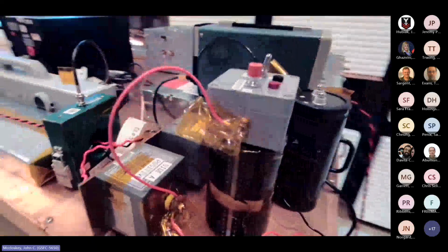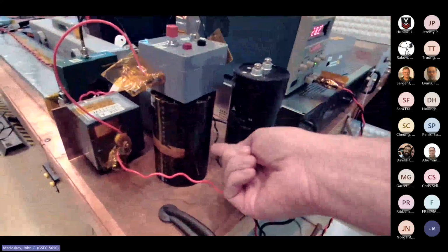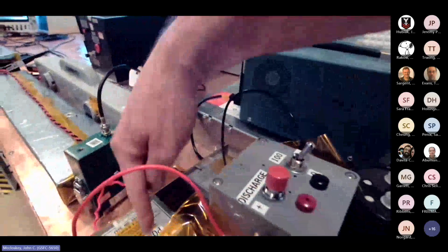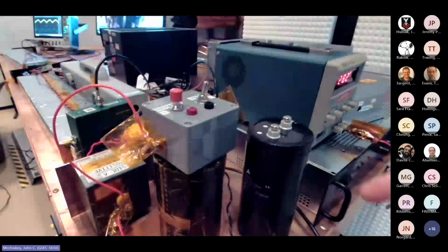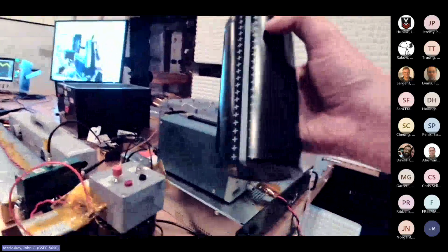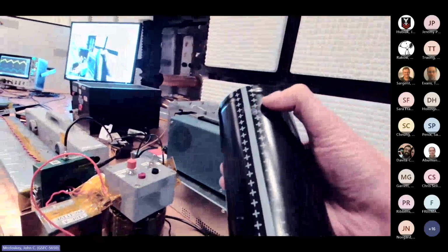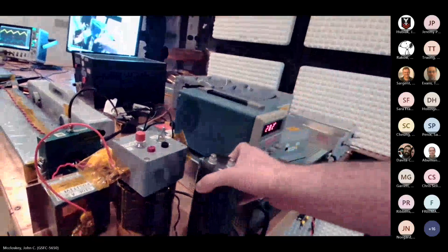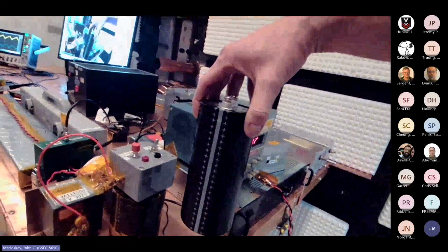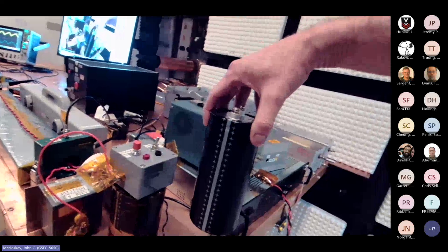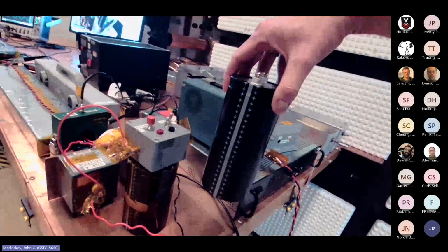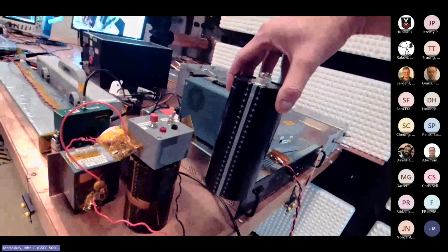The other part of this, for DC systems only, we put this 10,000 microfarad line-to-line capacitor across here. So it's tied between the positive and negative terminals. And I have a bare one here so you can see it a little better, but it's just a capacitor. It's polarized, so make sure you hook it up correctly. They very clearly mark the positive terminal here, which is also why you wouldn't want to use this on an AC power system, like 60 hertz facility power, because MIL-STD-461 applies to that too. It's just when we apply it to spacecraft, we're most of the time dealing with DC power.